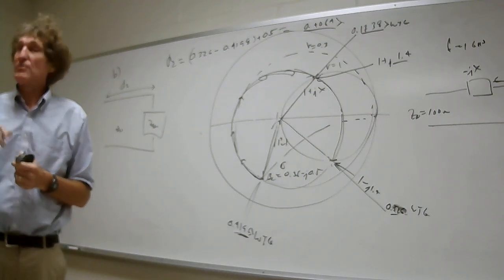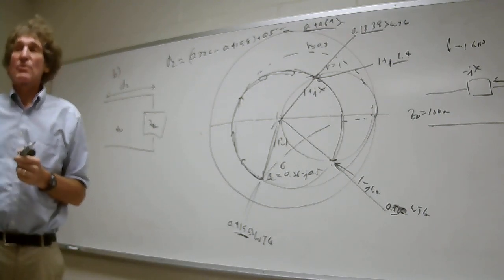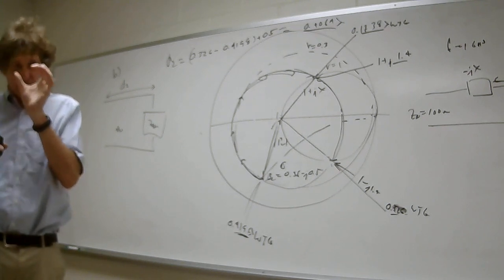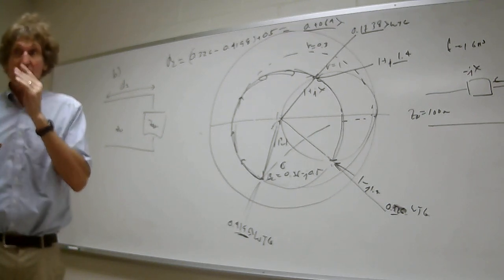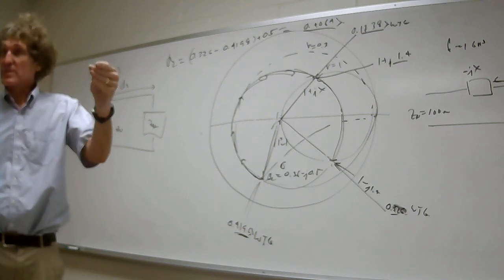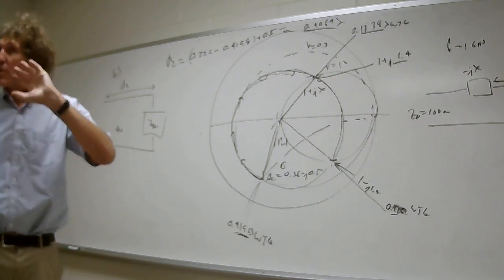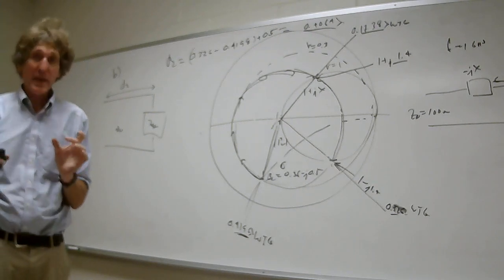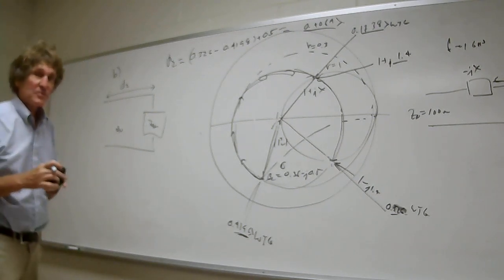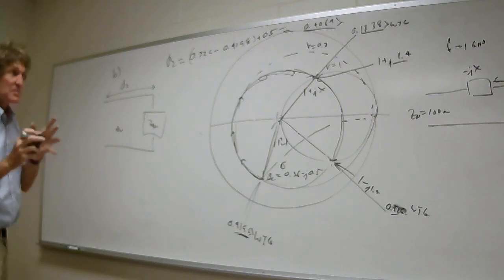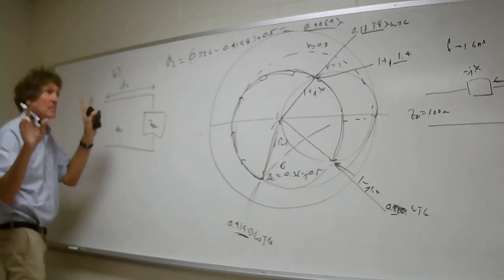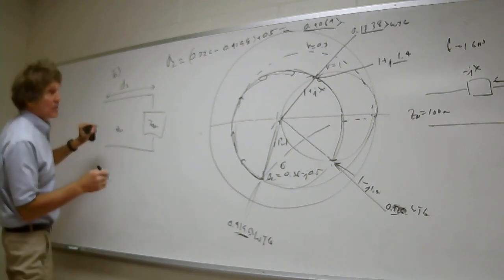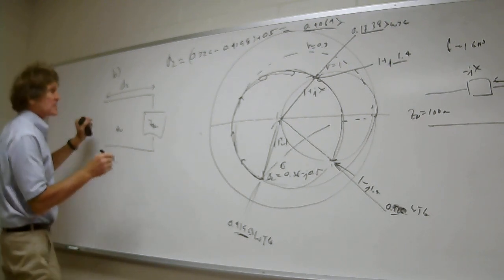Agree, class? By the way, you'll notice these matching networks only work at one frequency, technically. I mean, there is a bandwidth. There is some region of frequency, but because the wavelength is a function of frequency, these only work at technically one frequency. They have a small little bandwidth they work over. There's tricks where you can make it work over all frequencies, but this is not it. But this is the most commonly used matching network there is. So I move a total of 0.4064 lambda.